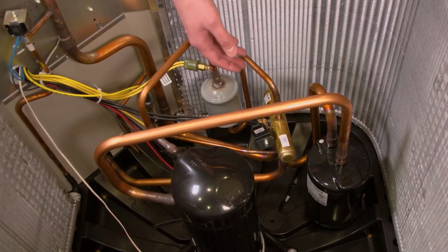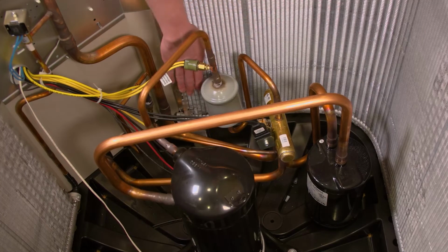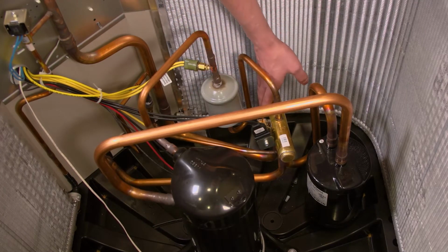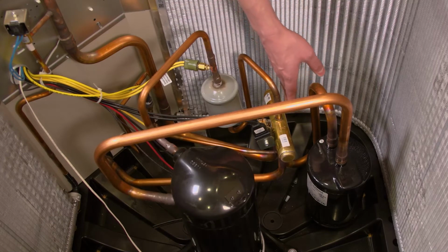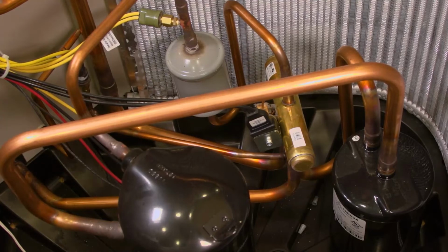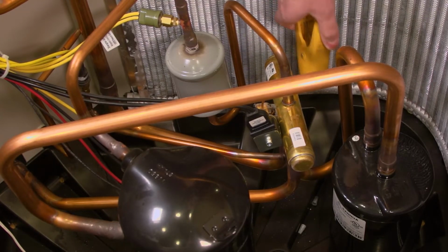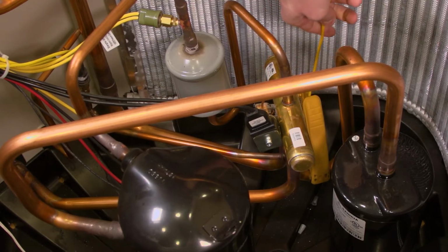Now, when it comes to placing your probes to test the reversing valve, you want to get as close to the valve as you can, because you're only dealing with a handful of degrees when testing your reversing valve. So what we're going to do here is we're going to use our thermal clamps from our digital gauge setup, and we're going to clip on to our common suction line.